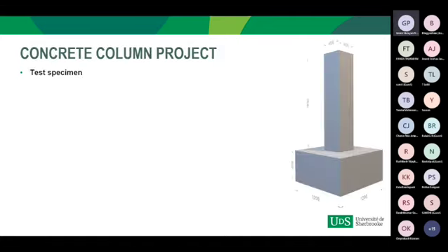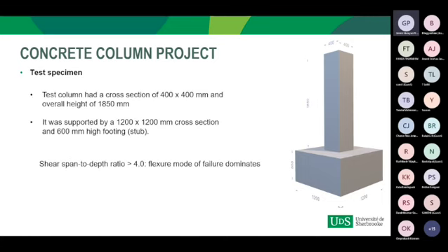Now, moving on to my graduation project, the primary objective was to study the behavior of concrete columns reinforced with glass fiber reinforced polymer bars subjected to quasi-static cyclic load, in terms of composite behavior, failure modes, deformability, and overall stiffness. I selected a full-scale test specimen which represents a ground floor column cut at mid height.